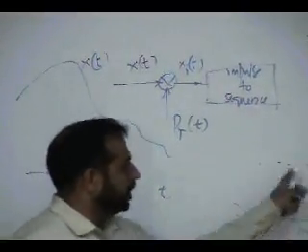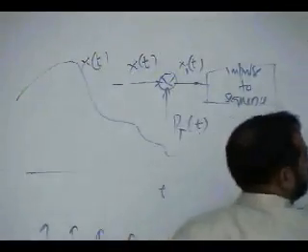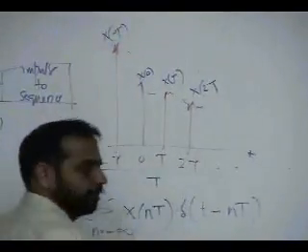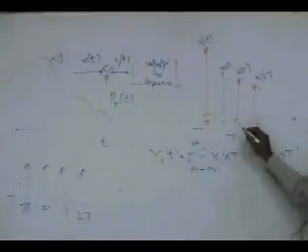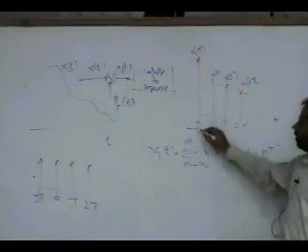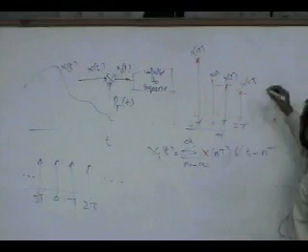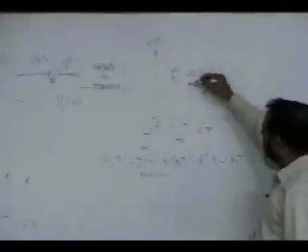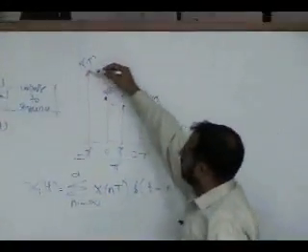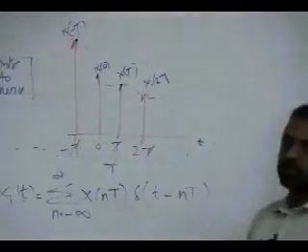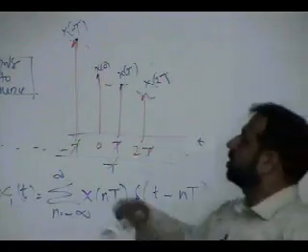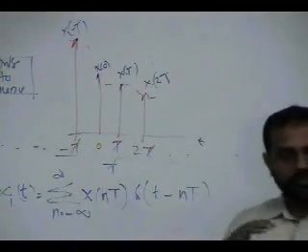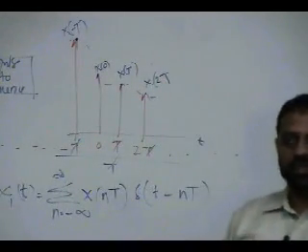Now take away time, divide the time axis by capital T. This will make it 1, 2, minus 1. And just record these values. So these are now digital impulses. This is what you do to get to this. So you take away time once you convert an impulse train to a sequence. Now you have a sequence of numbers.